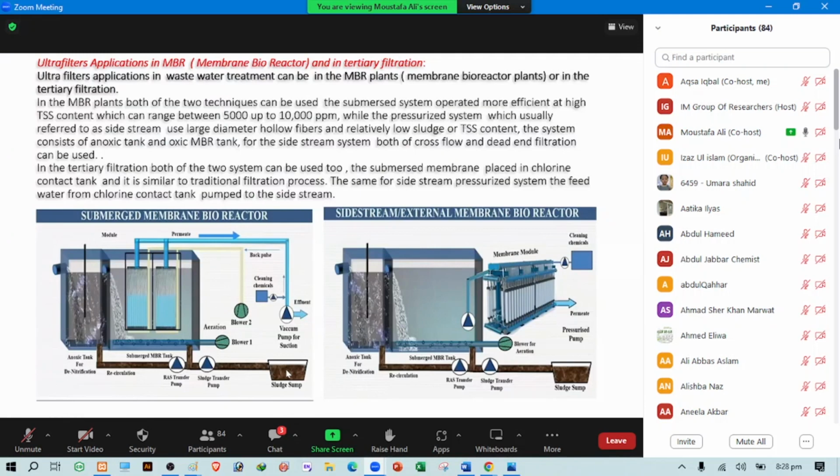As we see, the sludge collected in this tank has air diffusers to guarantee the depletion of organic matter. But from time to time we have to switch them off, because it's a continuous process with continuous removal of liquor from this tank to the sludge holding tank.